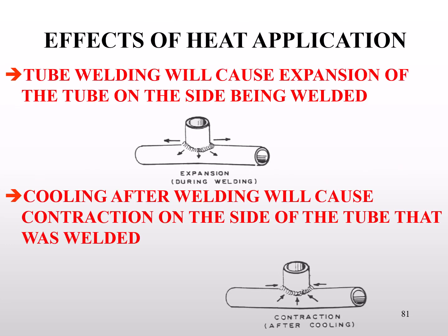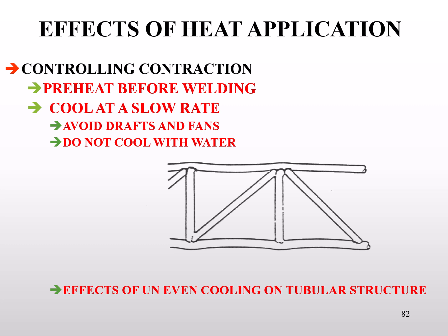Simple illustrations that give you kind of a feel for what's happening during the expansion phase, what's happening during the contraction phase. The methods you use help control this. This is what we've been saying. If we preheat before, tack before, while we're making our weld, we'll have more control over expansion. Then, after we're done with that weld, we're going to take the torch away slowly, control how quickly it shrinks, and we can eliminate a lot of this warping and buckling.